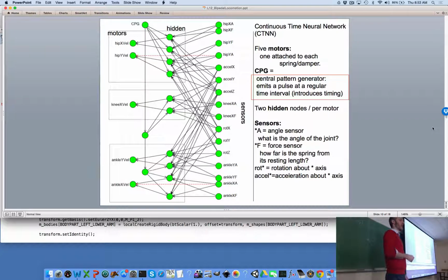So it'll minimize effort? It'll minimize energy expenditure? Not energy expenditure, right? That's still sort of, well, actually that might be, right? The more the sensors are connected to the neural network, the more non-zero values you're going to get arriving at the motor neuron. So that's true. The more sensory input, probably the less passive dynamic walking you're going to get. It won't break what we've already done because we haven't had input from them, so they've already been technically 0. Exactly, right? So up until this point, these have all been 0 already. If you suddenly make them large magnitude values, you're going to break these evolved connections here, right?